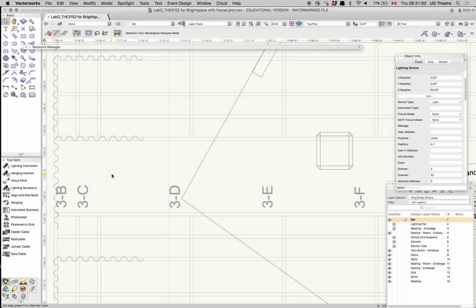There's a couple of different ways of doing this, but I'm going to show you one technique of creating a boom. If I was just hanging a regular pipe, there is a truss here next to my spotlight. There's a truss tool where I can insert a lighting pipe. Well, that's great if pipes are hanging horizontally, but if they're coming from the ground going up, it's a little bit more problematic. There's other things that you could use, but a technique that I like using is to actually draw a pipe and have it extrude up.